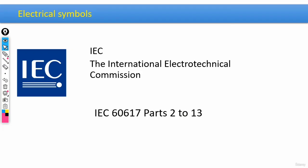Now, first off, guys, for drawing an electrical diagram, we have a variety of standards worldwide. One of the most important standards would be IEC, or International Electrotechnical Commission. IEC standard number 617, part 2 to 13, includes a database displaying the electrical symbols, and with the help of this database, we can draw our electrical diagrams.